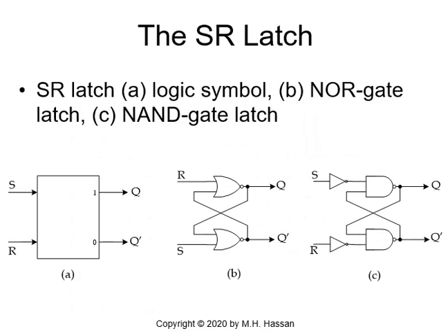Now let's study if Q is 1. Again we are applying 1 to the upper NAND gate from S, because S prime is 1 and R prime is 0. So Q is 1, Q prime is 0. Let's look at the lower NAND gate, 1 NAND 0, because R is 1, so we are NANDing with 0.